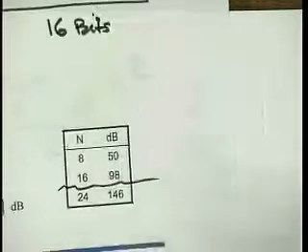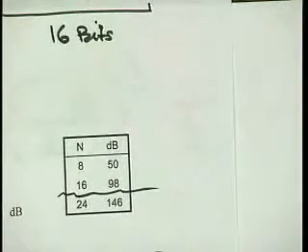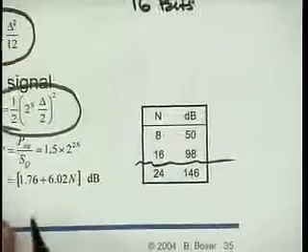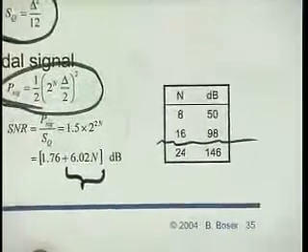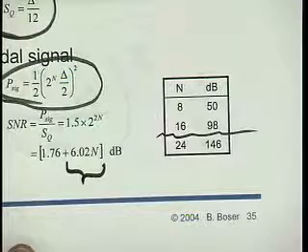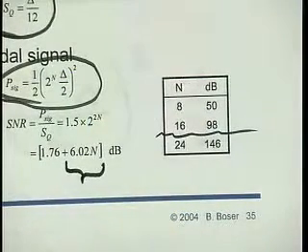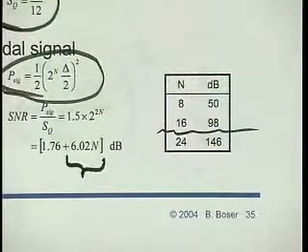But of course, there are miles of difference between 50 and 100 dB because we have a logarithmic scale. Right? Okay, another thing that is kind of buried in this equation, and that is really important here, is that for every bit I add, I get an additional 6 dB of signal-to-noise ratio.